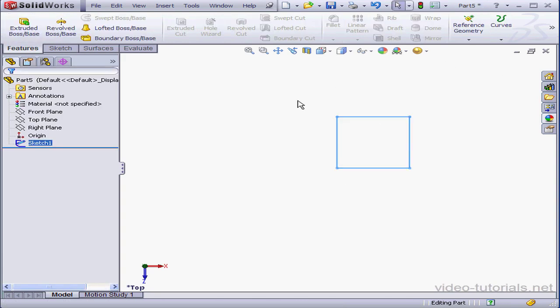And let's exit the sketch. It's a good idea to rename the sketch as well to make it easier to recognize from which entity the dimensions that you're working with come. Give it a slow double click to activate the rename field, and then press Enter to accept your new name.